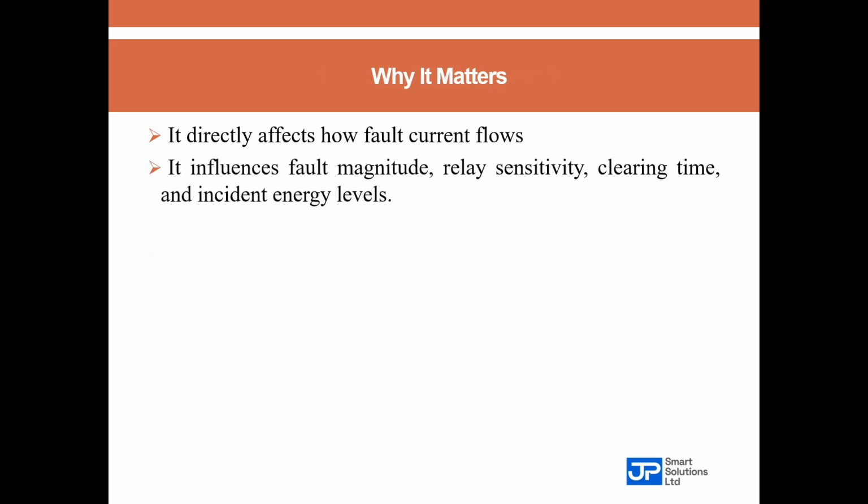Next, it influences the fault magnitude. And if it influences the fault magnitude, it means that it also influences the relay sensitivity. If it is influencing the relay sensitivity, it means that it is also influencing the fault clearing time. If it is influencing the fault clearing time, then it also means that it is influencing the incident energy level. That is when we come to arc flash assessment and mitigation.